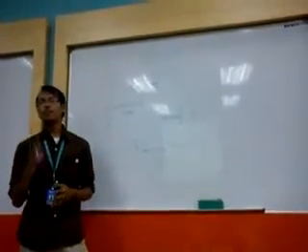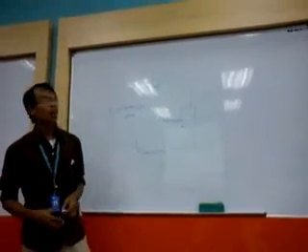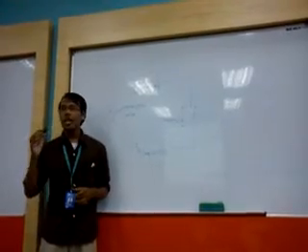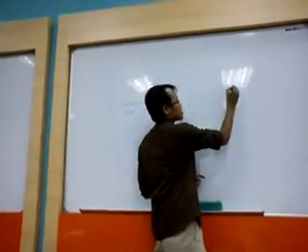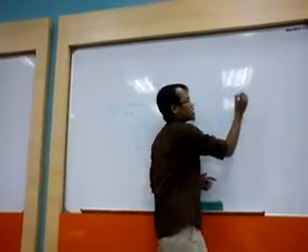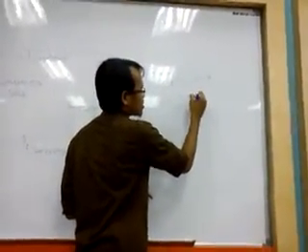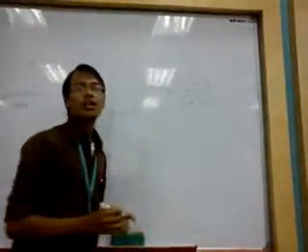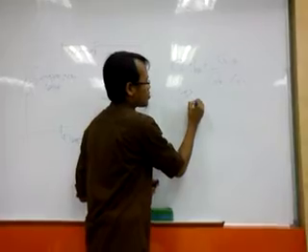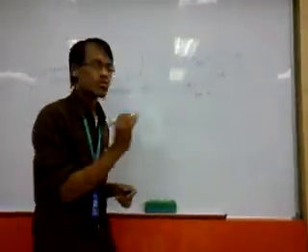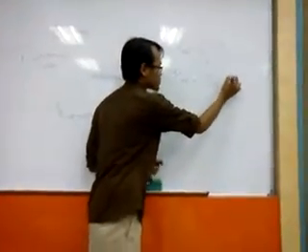The measure of performance of a heat pump is also expressed in terms of the coefficient of performance, which is COP-HP, defined as COP-HP equals QH over QH minus QL. And other than that, we can express COP-HP as equal to COP-R plus 1.